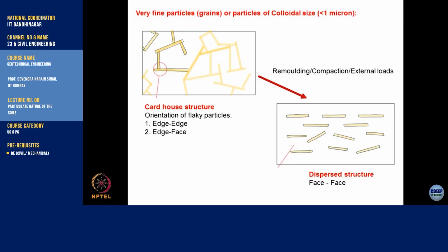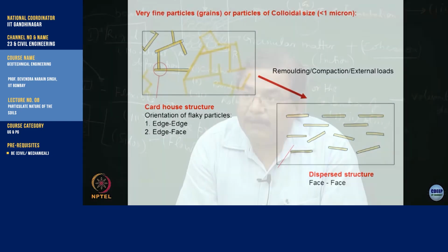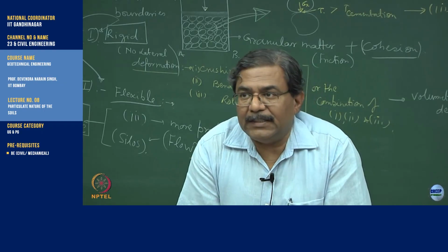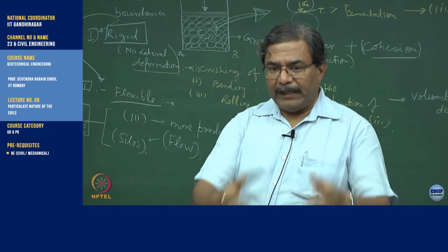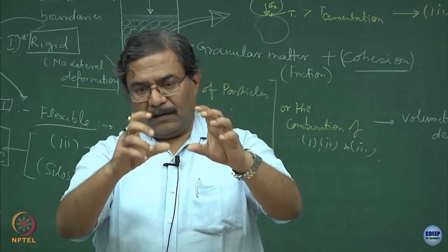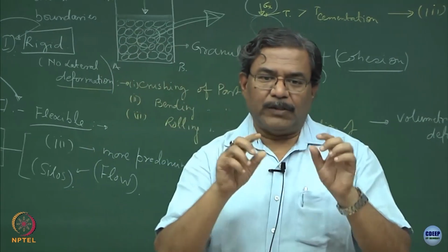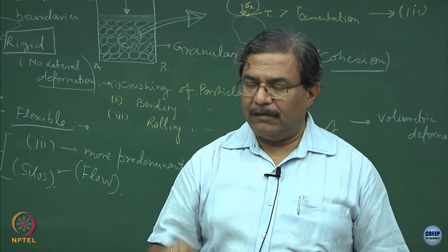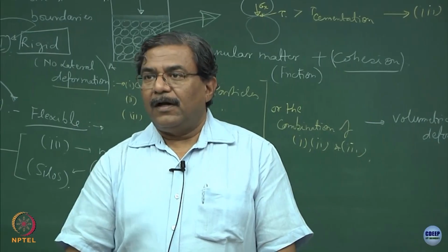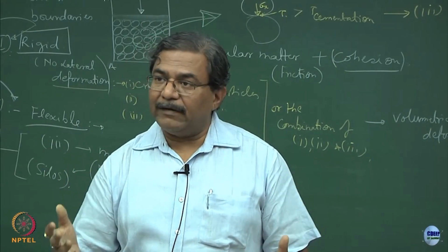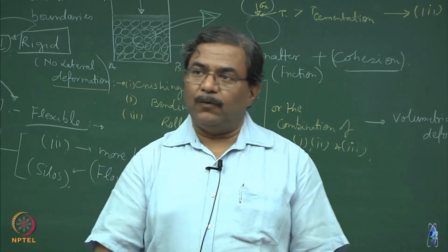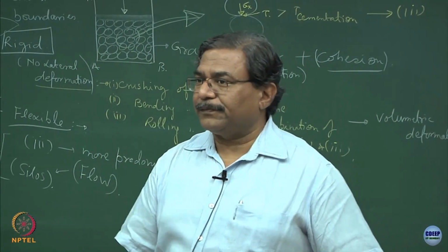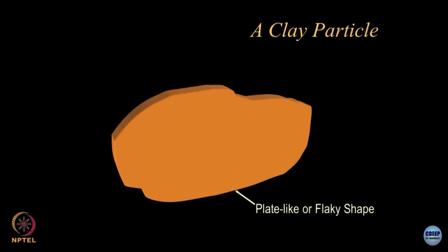Quick answer to your question would be: permeability is dependent upon the porosity. Porosity is a fundamental property of the grains of the soils. So, if I take out a sample of the soil, and I want to see what the porous space is, that quantification is porosity. We will do it today, clear. And hydraulic conductivity is a measure of how easily water can pass through a matrix of soil mass.